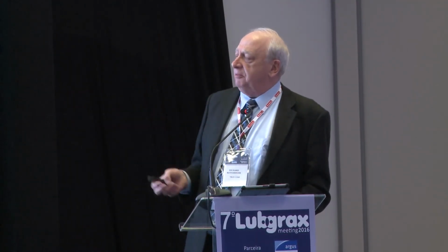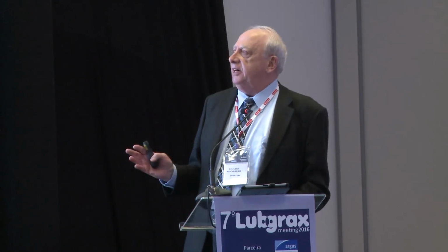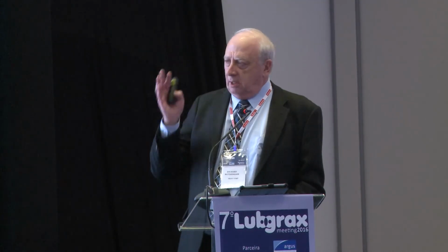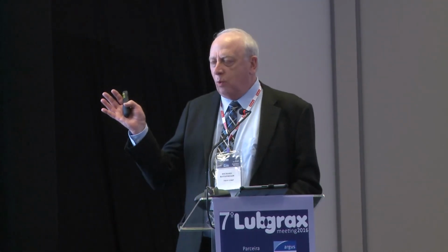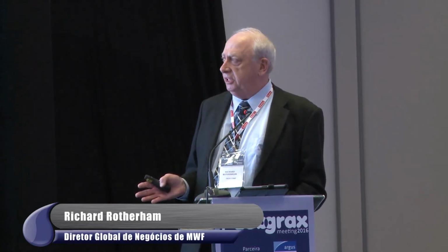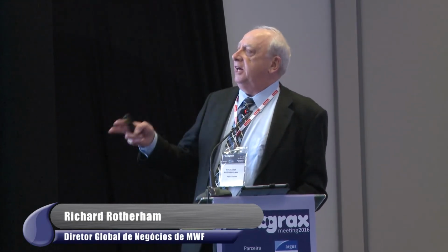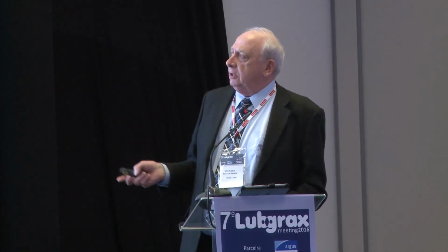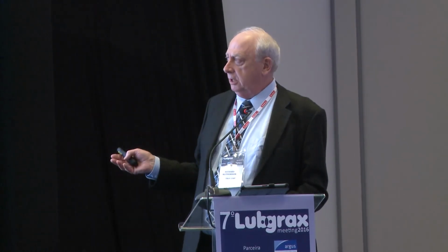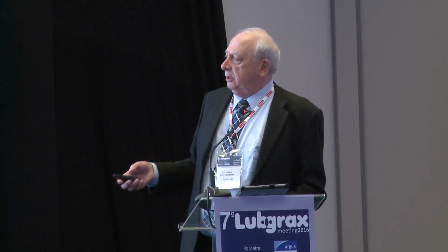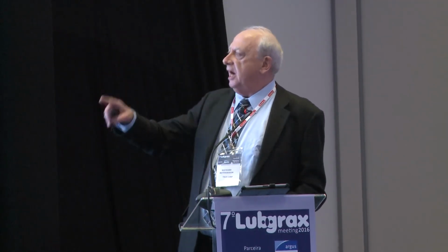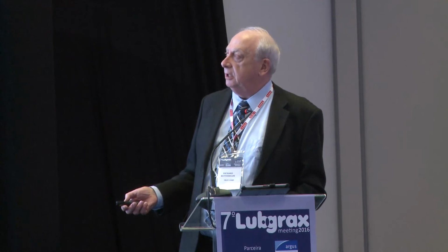So, actions to take before adding any biocide: try to identify and control any sources of contamination. If you know the water supply, because we have plants that use well water, for instance, that has contamination in it, or river water that's been untreated, try to get them to treat it before it comes in. Control tramp oil in the metalworking fluid. Tramp oil promotes anaerobic conditions, so that's never good. Keep the fluid circulating, because that avoids anaerobic conditions again. Adjust the fluid pH if necessary. Ideally, do that before you add the biocides.